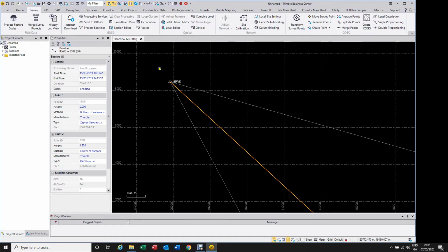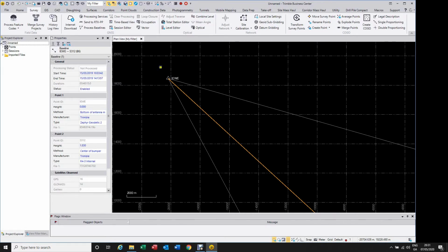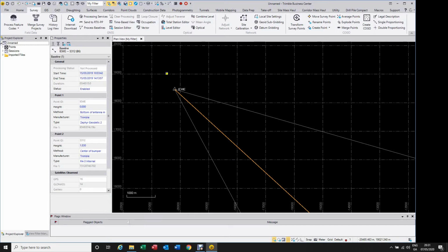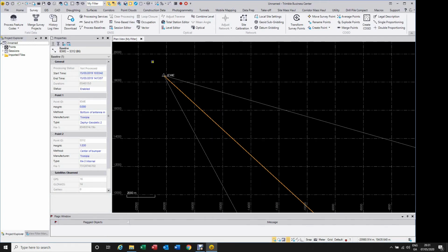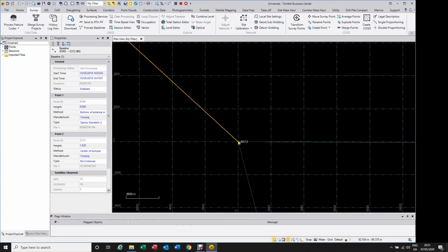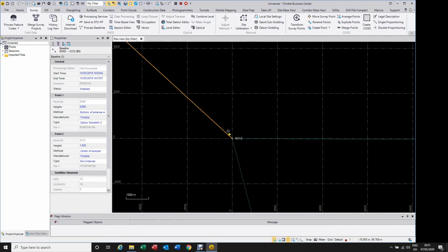So the system knows that at that time, because of some ionospheric disturbance, or a clock error or something, this position was placed here instead of here. So using this vector to fix the positions of this point, wherever it was observed at the same time, it knows that it can't be there, so it's most likely somewhere here.